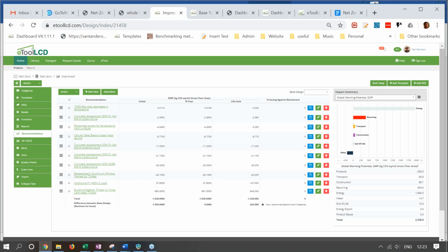Sometimes it has a saving in cost because you're saving in structure. It's a lightweight material, so you're saving on foundations. It depends on the design and the design team. But it's an extra motivation, some more incentive to look at low carbon materials, and particularly, I think, for the big savings, going for mass timber in the superstructure and framework.